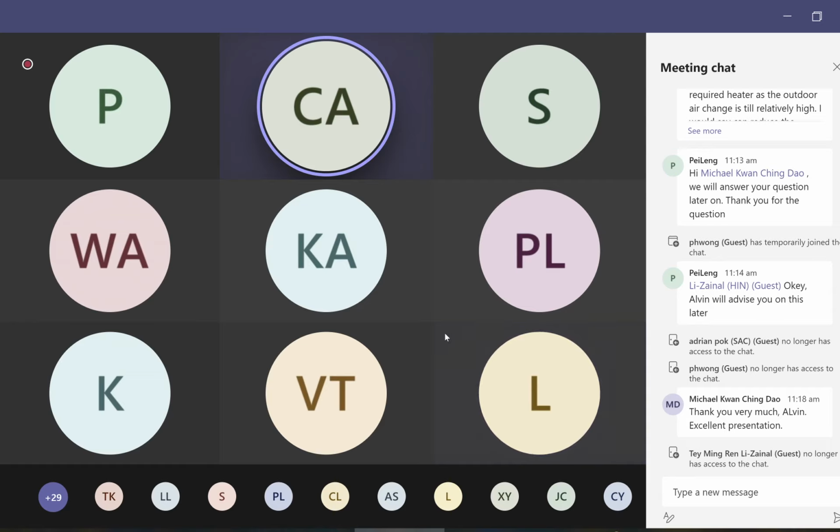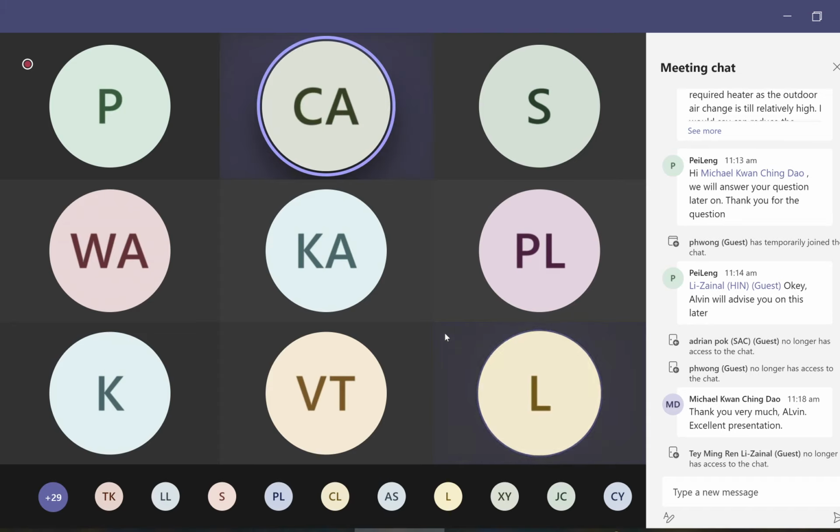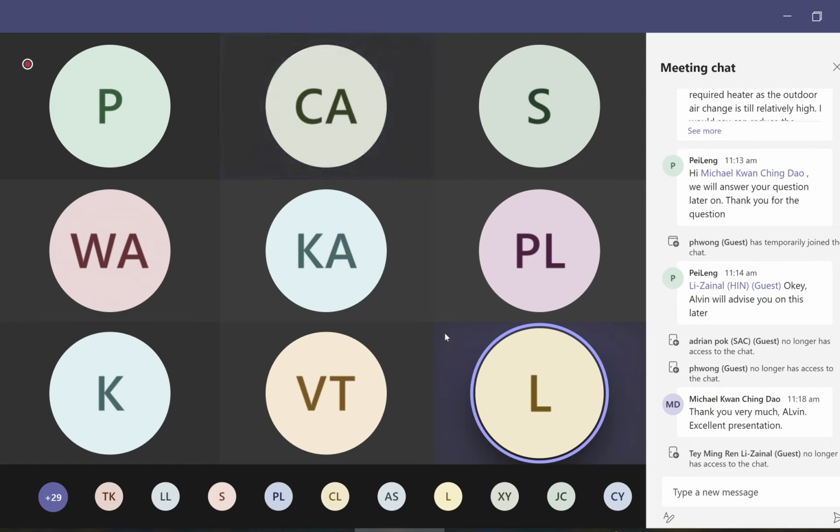So like your case, if you are using a CAV system and there are some VAV in that CAV system. No, it's a VAV. It's a full VAV system. It's not a mix of CAV. Why I'm saying that is because just now you mentioned bypass. You will only use bypass if you have a CAV system, but there are some zones which are VAV. Then bypass is maybe a proposal to mitigate this, but not the system that we use. What we're facing is the VAV system.